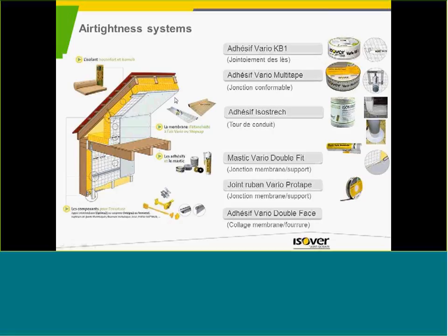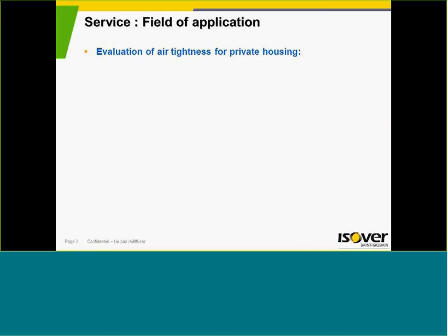All these components are made to help the workers to realize a good airtightness system in individual houses. And after that, in France, we have different rules, and we have to measure the airtightness in the house at the reception of the house. When the house is completely finished, we have to measure the airtightness, and the measurement is realized in Q4.